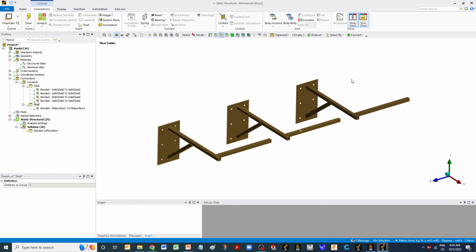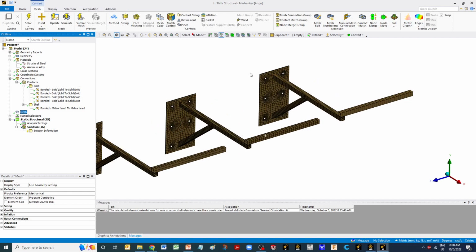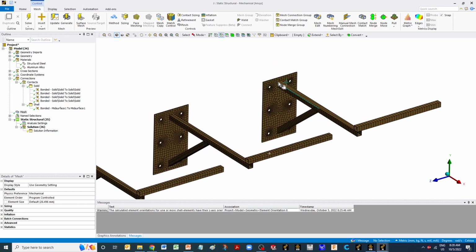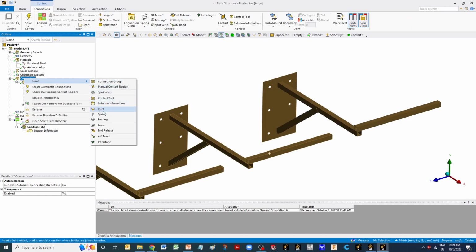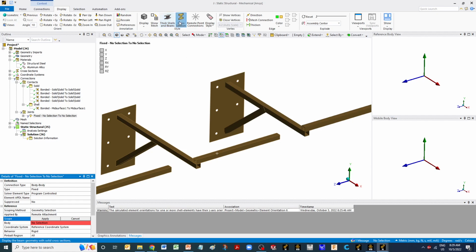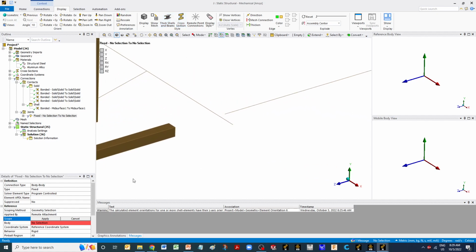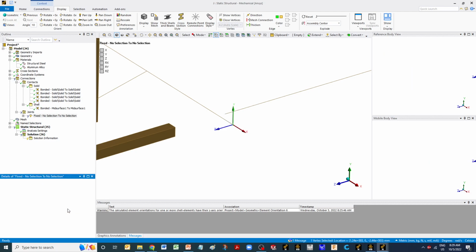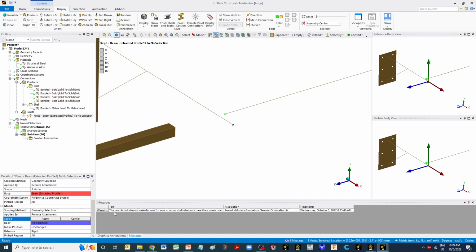So likewise for the beam elements, we have a conformal mesh here and at this location, but not this one here. So I need a joint to connect this node to this node. So let me do that. So I'm picking the vertex selection here. Pick this one, and then this one here.